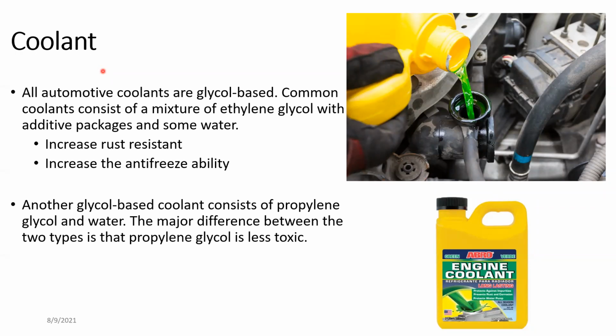Basically, most of the time, normal day-to-day vehicles usually use the green color one, given with particular coolant ratings, and it's mixed with water. When we are mixing with water, it's not just tap water, it has to be distilled water. It should always be distilled water. Mixing it with normal water will affect the coolant. Distilled water means battery water, usually called battery water. So it has to be mixed with battery water.